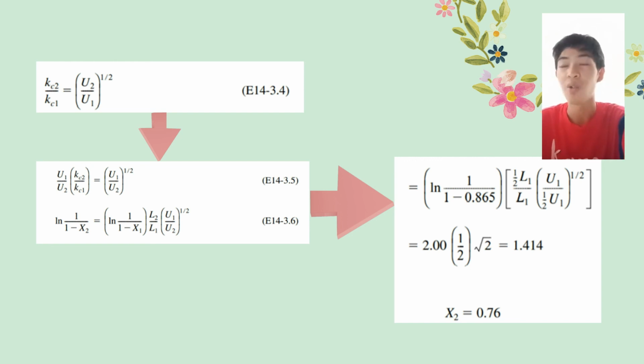Consequently, we see that although the divided arrangement will have the advantage of a smaller pressure drop across the bed, it is a bad idea in terms of conversion. But we need to recall that if the reaction were reaction rate limited, both arrangements would give the same conversion.